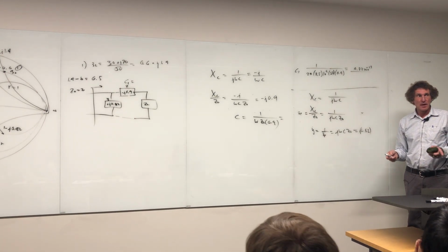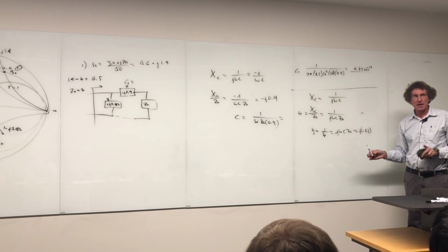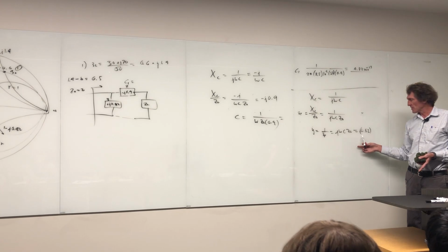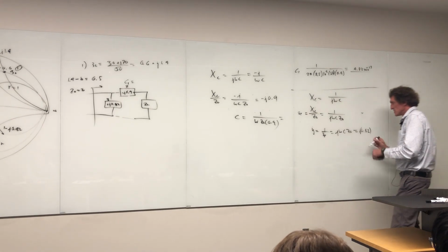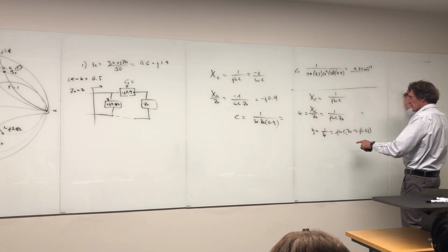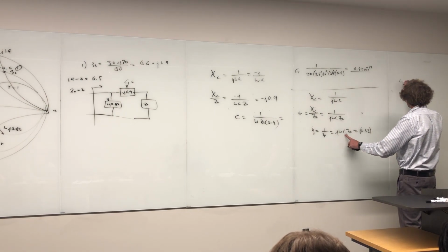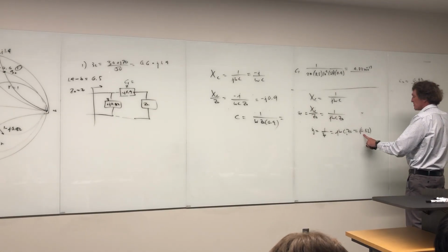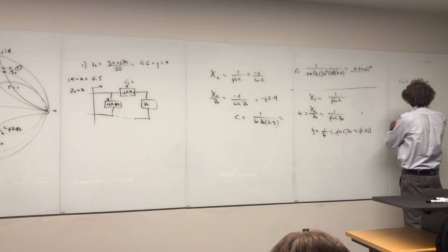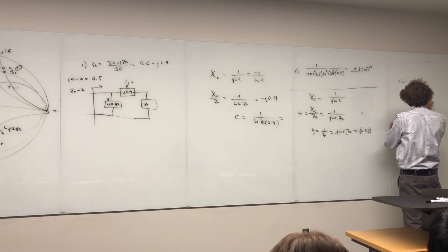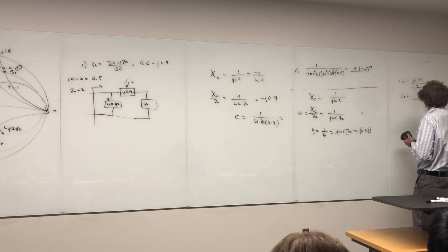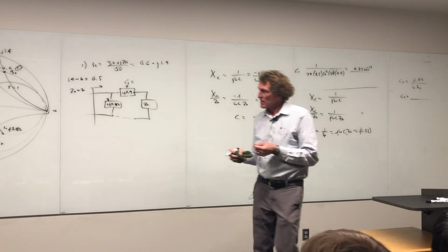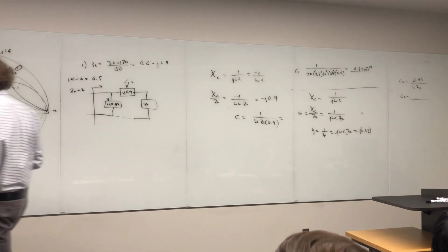Now here, I casually say you see the J's go away and stuff like this. I'm going to just show you. If we go ahead and divide by J, they go away, right? The only thing we're solving for is C. So this will be C2. And when we take a look at this, that means C2 here is equal to 0.82 divided by Z naught omega, or omega Z naught. And that means C2 here, and you can give me that. Omega is 2 pi times 2.5 gigahertz, right? I have 7.5, it's 2.5.